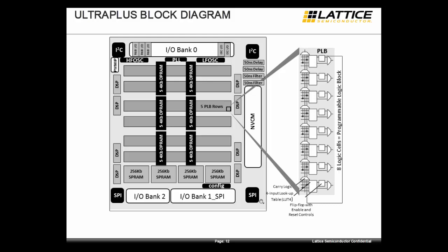These are standard iCE40 and SPI blocks where the logic of these are in hard format inside the FPGA, and the user, all they need to do is to instantiate these blocks and make use of them in their logic. The device is comprised of 8 DSP blocks, and these are full functional DSP blocks.